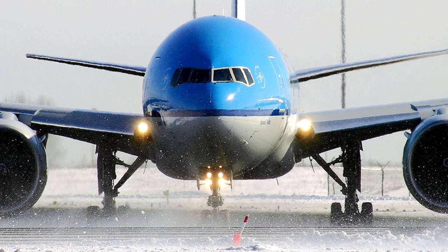Lastly, there are two important points to consider about the certified performance of an aeroplane on a wet or contaminated runway. Firstly, the use of reverse thrust is allowed for the determination of the accelerate-stop distance, whereas it is forbidden to be taken into account for the accelerate-stop distance determination on dry runways.